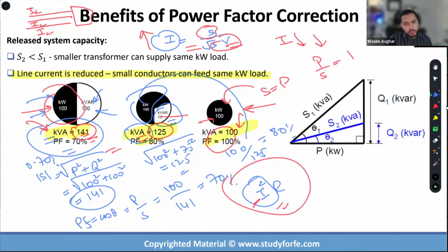And the fine details of how you actually manage the power factor correction can take so many different shapes and forms. You can have capacitors going in, going out all the time. In some cases, you may also have to do load shedding. In some cases, you may actually have to respond to the conditions upstream at the utility level. Because if the utility is doing some sort of power factor correction and they have a capacitor engaged, then at your load you can have higher voltages on your line.